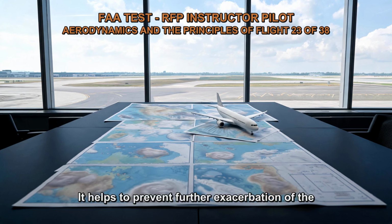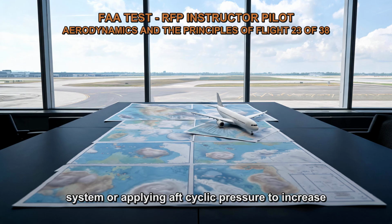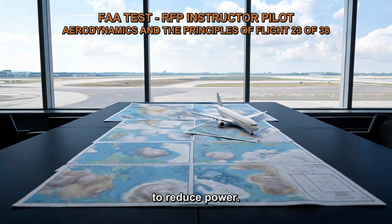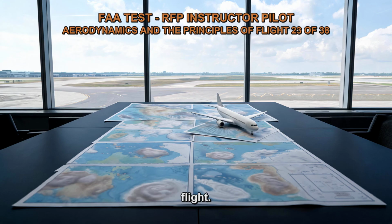It helps to prevent further exacerbation of the oscillations and allows the pilot to stabilize the aircraft. In contrast, options that involve unloading the rotor system or applying aft cyclic pressure to increase pitch and reduce airspeed may not directly address the root cause of the oscillations and could potentially worsen the situation. Therefore, the recommended first action to take if a gyroplane begins to oscillate in flight is to reduce power. This enables the pilot to regain control and stabilize the aircraft, ensuring a safe and controlled flight.